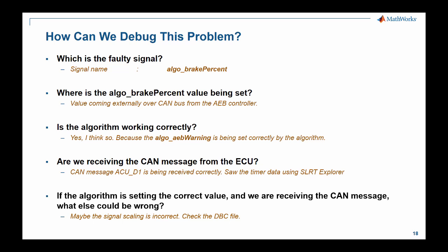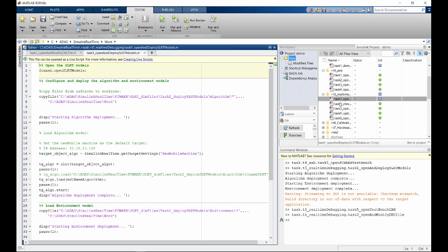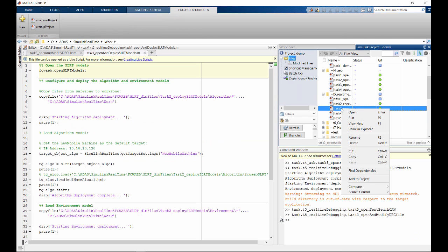And while the CAN DBC files themselves are the standard database files which store the CAN message and signal definitions, the signal scaling and offset within them can change very often during the development cycle. This happens all the time. And in fact, that is exactly what the problem was in our case.